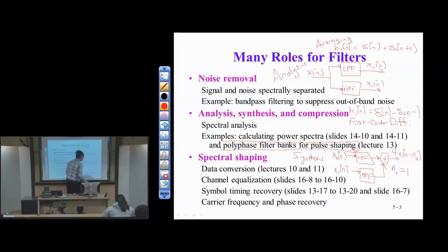So why do you filter x0 and x1 before summing them together? Well, this is the general approach, and this would handle things like if there's noise, or I do some additional filtering between here and here. If I didn't alter x0 or x1, all I'd have to do is add them together. And you can see that, because if I add them together and I add the impulses together, these two terms subtract out. I'm just left with the impulse. I'm left with an identity system.